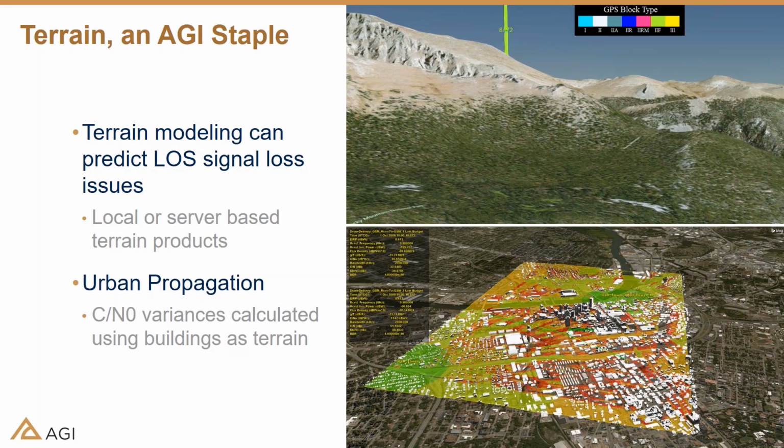In the picture in the upper right, you can see PRN8 following its path down below the mountain there. The receiver, I don't know if I mentioned this earlier, but receivers typically have a constant 5-degree mask angle above the horizon and all 360 degrees azimuth around you. Below this 5 degrees, your receiver is not going to look for any satellite signals, because as those signals travel through the atmosphere, they get additional errors that the models in the receiver can't correct for.